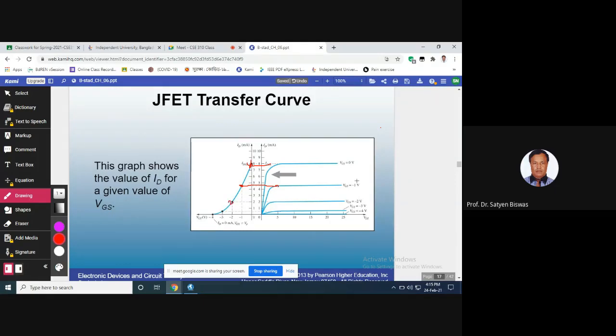And gradually you decrease the VGS and you find several curves and then extend the saturation current. In here, this is the value of the saturation current, and you extend this line to wherever you get. You see? No, okay. Maybe I did not explain clearly.